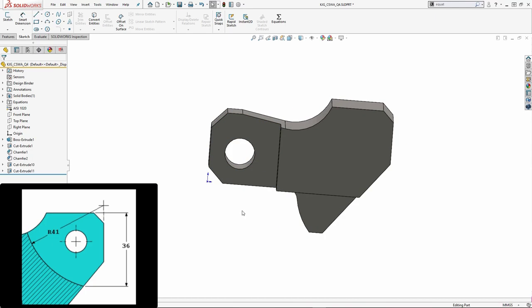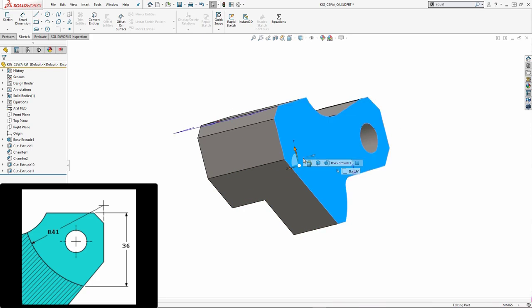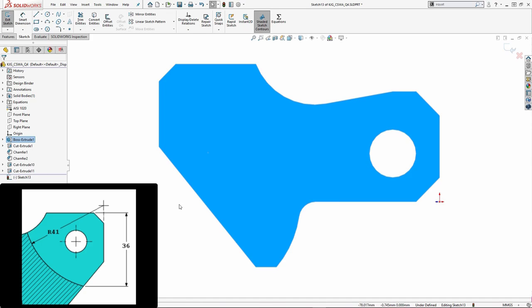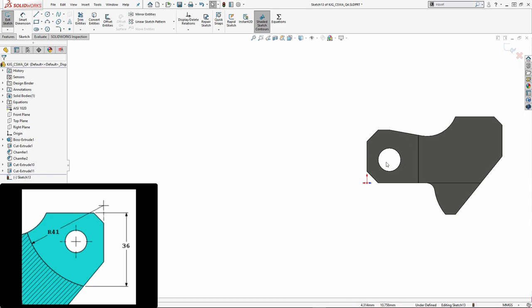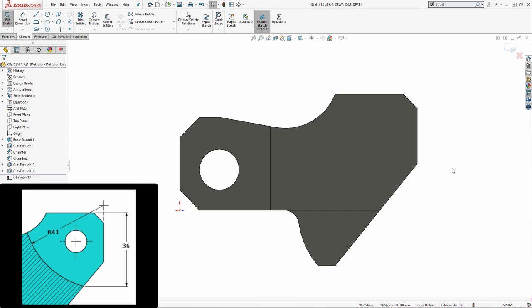The next cut that I'm going to address is going to be that radial cut. Now we know that it's not going to be symmetrical through the middle of the part. I'm going to sketch this on the back side of the part. Now, I like items to be oriented the same way that they are when I'm taking the test. It's just one less thing for me to have to remember. So I can right click on my sketch and then say normal to in the tree, and that will flip this so my orientation is correct. I'm still sketching on that back face though.